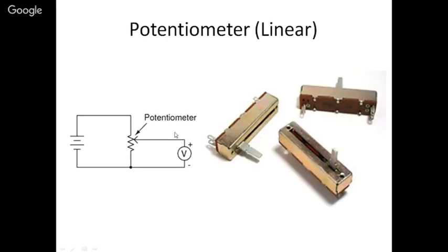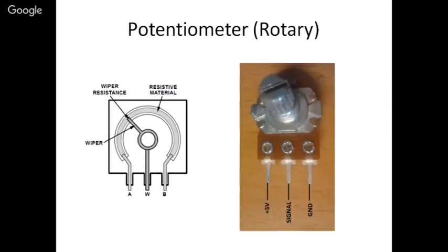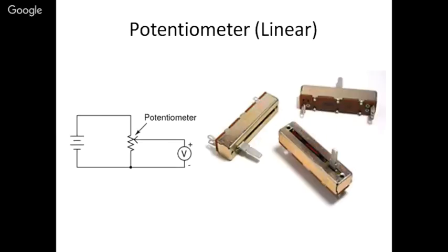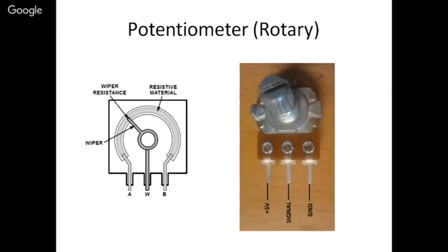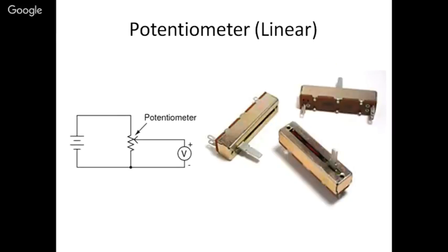That is how they are numbered on the back of the linear potentiometers, or for that matter rotary potentiometers, because a throttle position sensor will be measuring an angular displacement. So for that, rotary potentiometers are used. The principle is the same. Why we showed you this was because, number one, potentiometers are of two types, linear and rotary, and number two, we will just demonstrate a linear potentiometer here.